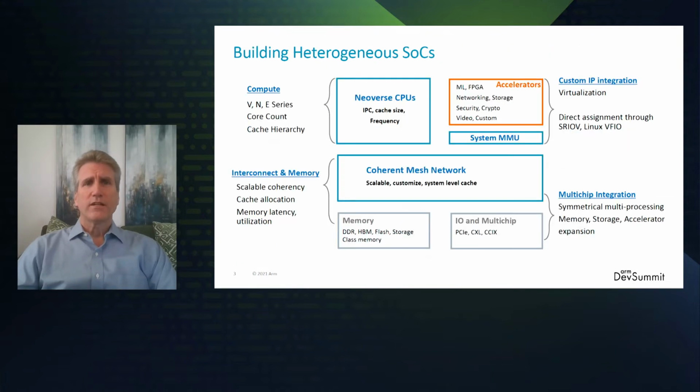These different size SoCs can have a range of compute elements and accelerators either in or connected to the interconnect. There'll be a mix of CPUs, NPUs, GPUs, ML, crypto, and I/O masters that can attach to a variety of memory, cache, and other configurations. The interconnect must maintain cache coherency for hundreds of CPUs and I/O and accelerators. And we'll also have multiple chip connections with different topologies to support, and PCI Express and so forth. The interconnect must be, like I said, efficient, scalable, low power, and minimal area in these SoC designs.